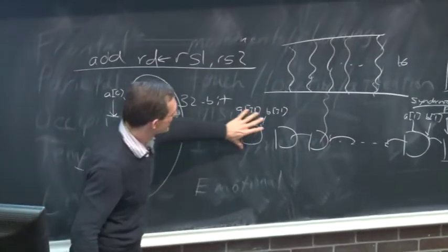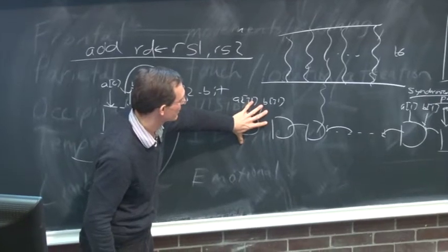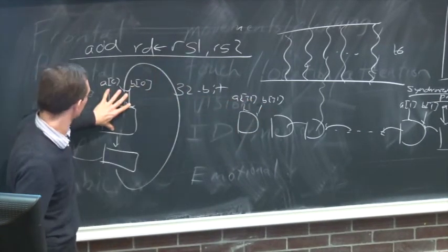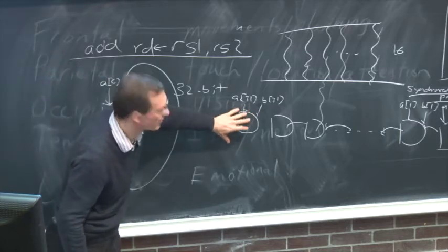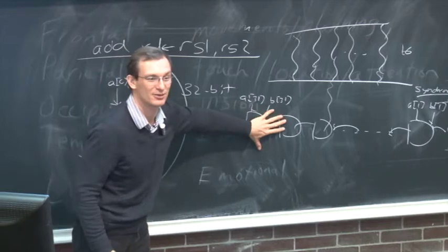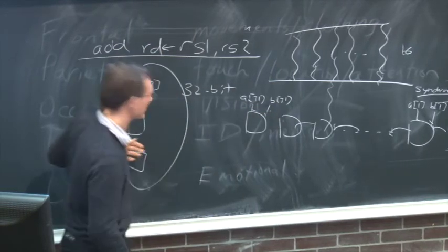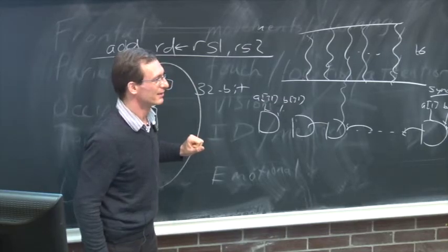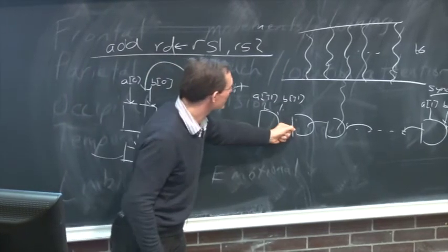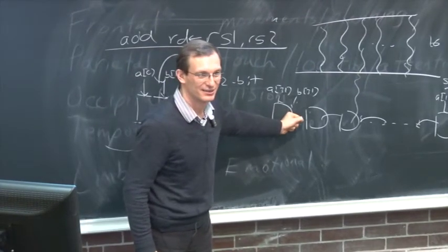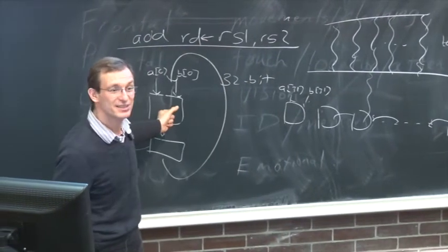What's the trade-off? This adder implementation, a lot of hardware. This adder implementation, well, maybe almost 1/32, like 3% of the hardware cost of this one, almost. Maybe 5%, let's say, because you have some additional logic here. So low cost, high cost. Slow, fast. And people have used bit serial adders.